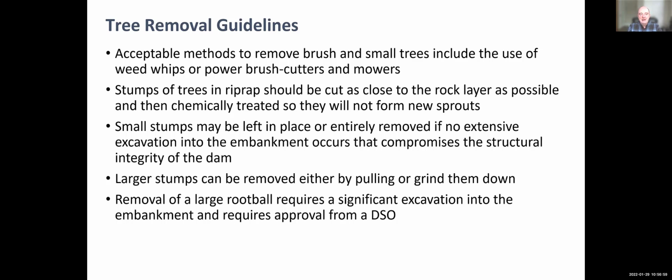Aaron and I struggled to find any guidance as to what chemicals are allowed for that purpose. So there's room for the dam safety section in this province, or even in the country, to come up with better guidelines for what we are allowed to use. If you're in the riprap on the upstream surface, you're very close to the water, and you're not allowed to put any herbicides into water typically. If any of you have had personal experience with a chemical you were given permission to use, definitely slide that into the chat because we would learn from that ourselves.